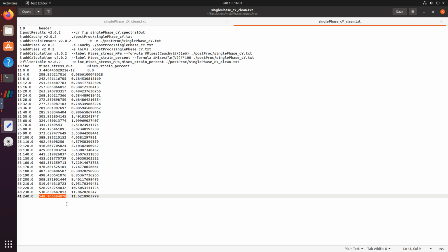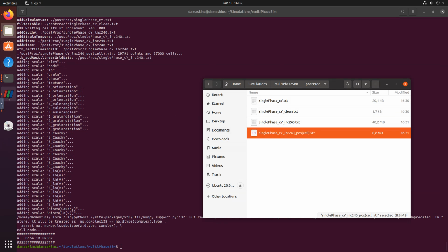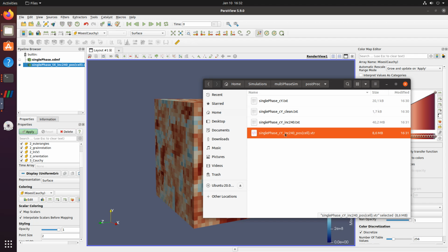So you see that we did not change any orientation of the material. Something that we did was we applied compressive load instead of tensile load, and therefore you see a small difference in the amount of strain that happened in the material because different slip systems activated. If I ran it in tension, it would be extremely close to 10.4, somewhere there, right? But yeah, you see the global results, and then I think the local results have also processed, and we can see that. And what I will do is I will quickly import this file here.